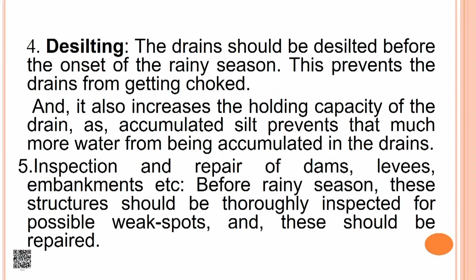Desilting: drains should be desilted before the onset of the rainy season, and now our government is also trying to clean the drains before the rainy season. This also prevents the drains from getting choked, and it also increases the water holding capacity of the drain, as accumulated silt prevents that much more water from being accumulated in the drains.